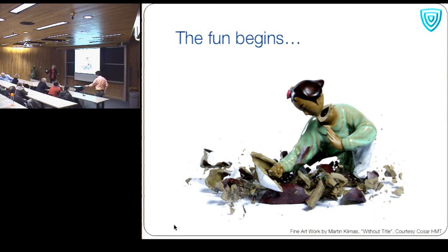So they're not able to reach their equilibrium length. They're taking off, but they can't take off at infinite speed. And what's happening at these high rates is the loading is happening so fast that the crack length doesn't have time to catch up. So it is, in a sense, unstable crack growth, but the fact that it can only happen at a finite speed keeps that from becoming a problem for us. Yeah. Sorry, go ahead.